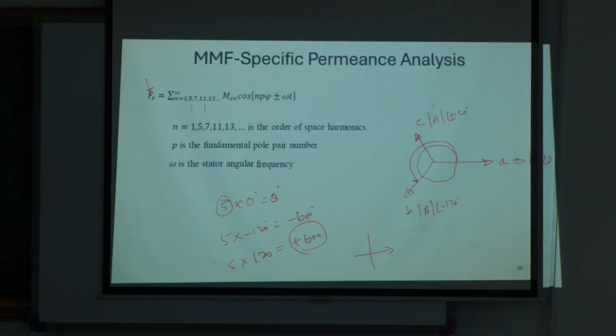So you see here the phase C component, when it comes to 5th order harmonic, would be at negative 120 degrees with respect to its reference phase. Whereas phase B harmonic, when it comes to 5th order, would be at this orientation. So minus 600 means you have to go clockwise, right?